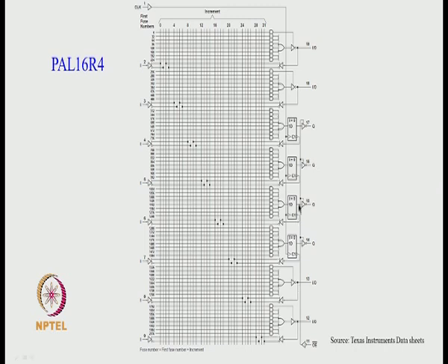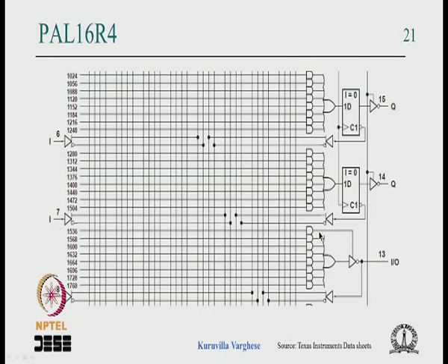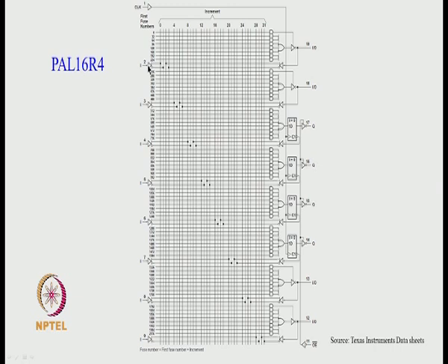What remains to see is a data path. A data path is a register, then the output of that goes to a combinational logic, then followed by a register. So even a data path in principle can be done, although there are hardly any registers here. Suppose you think of 8 bits, it is not possible, but I am showing 1 bit. If there were 8 registers, at least you can think of 4 registers followed by some computation in the combinational circuit, followed by 4 registers, which can be done in this structure. So this is an expansion of it, PAL 16R4. As I said, there are a maximum of 16 inputs, because there are pins 2 to 9, which is 8, plus 8 more, so 8 plus 8 is 16 inputs, and 4 registers, that is what the 16 is for.